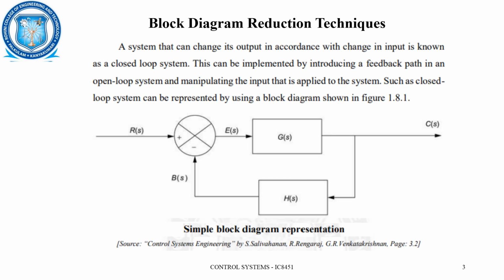Block diagrams are the representations of the transfer function of a system, the input to a system, and all the operations which are being performed in a system. This is what we are going to represent in the form of a block diagram, so that the calculations can be made easily. We are calculating transfer functions, we are writing differential equations, and then we may be supposed to use a state space model. We have a number of techniques in order to calculate. So these calculations can be made only when the system representation is made in a possible manner. For that purpose, we are going to use the block diagram reduction technique.